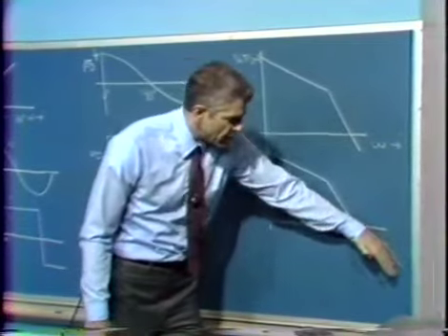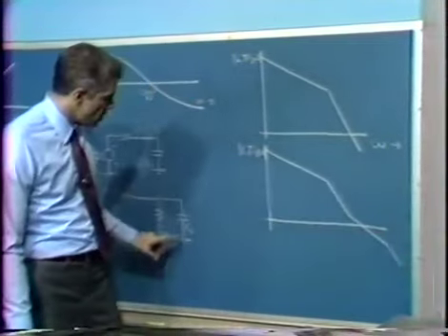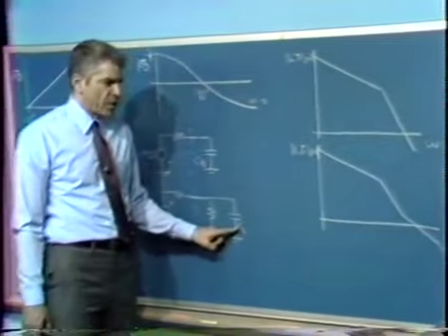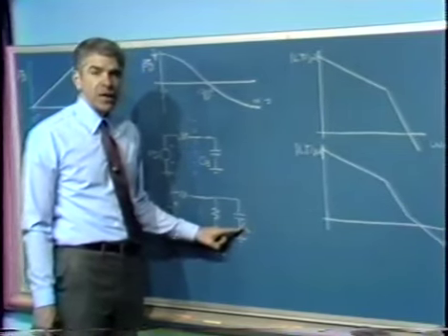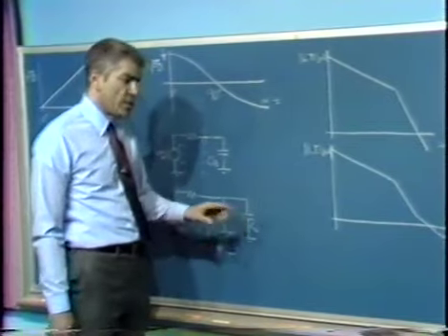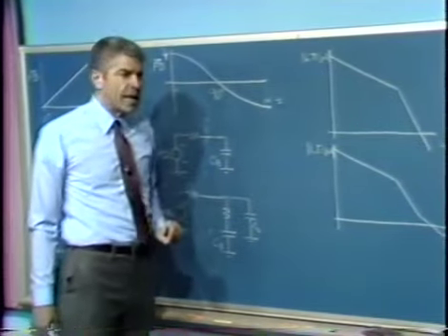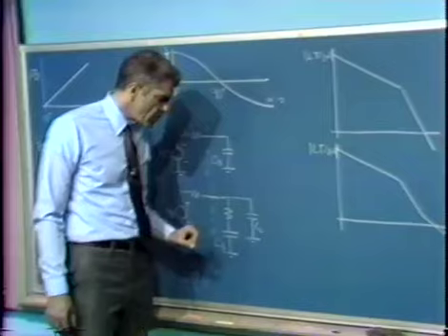And then finally, at a frequency well beyond crossover, we get the filtering action of the small capacitor, and presumably we choose the value of that capacitor so that it provides adequate filtering to the residual ripple out of the phase detector.